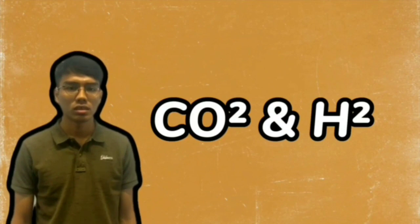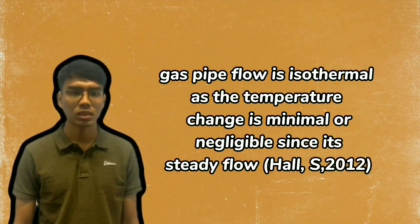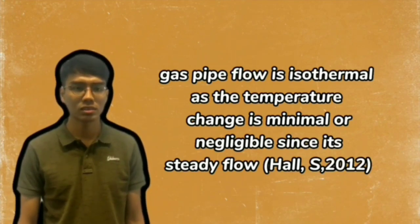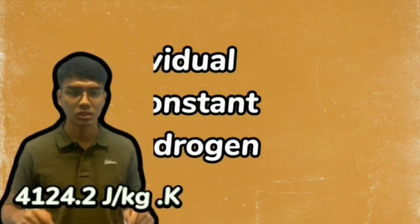As this pipeline has gas flow, we decided to use compressible fluid calculation for the gas flow. We use isothermal gas flow to calculate the pressure drop across all the pipelines. This is because most of the gas pipe flow is isothermal, as the temperature change is minimal or negligible since it's steady flow. First, we assume that carbon dioxide is negligible to simplify the calculation. Thus, we use the hydrogen gas constant.